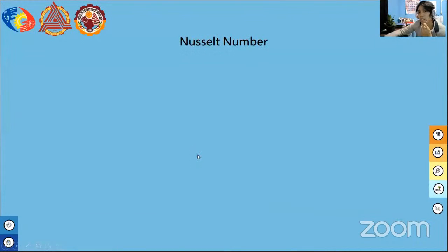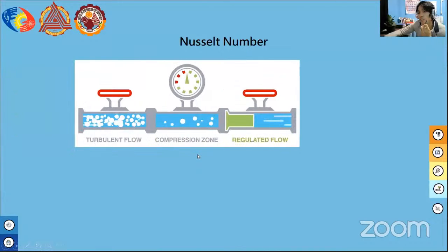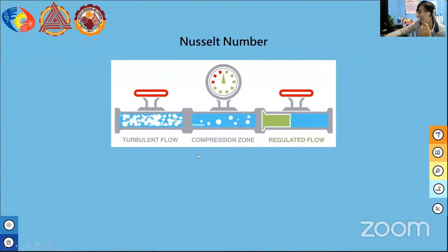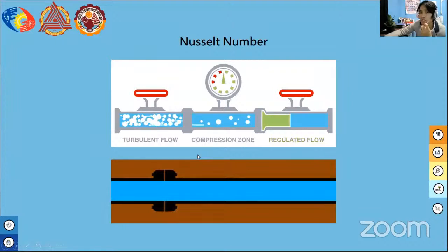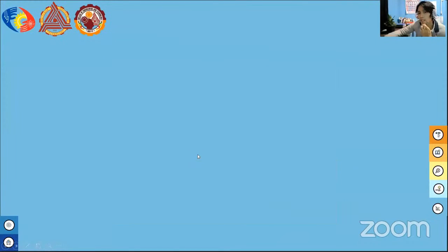Before we discuss Nusselt number results, let us first review the significance of the Nusselt number. The Nusselt number is the ratio of heat transferred owing to fluid in motion to heat transferred if the fluid was still or motionless. This shows how much the heat transfer is boosted by means of fluid motion. The Nusselt number refers to the quality of heat transfer rather than quantity. Thus, one can relate similar configurations and still be proficient in evaluating the heat transfer capability.